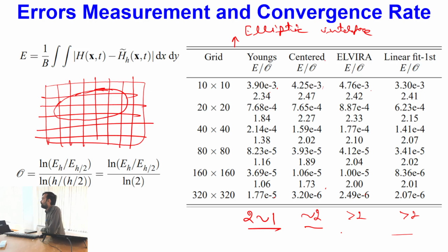Once we have an idea about the interface reconstruction methods, our next task will be to study what we do once we have reconstructed. What is the next step of the finite volume method, of the volume of fluid method? The next step is, once we have reconstructed the interface, we have to advect that to the new time step, depending upon the interface velocity, how it will advect with time. So in the second step we now need to learn about the interface advection techniques.